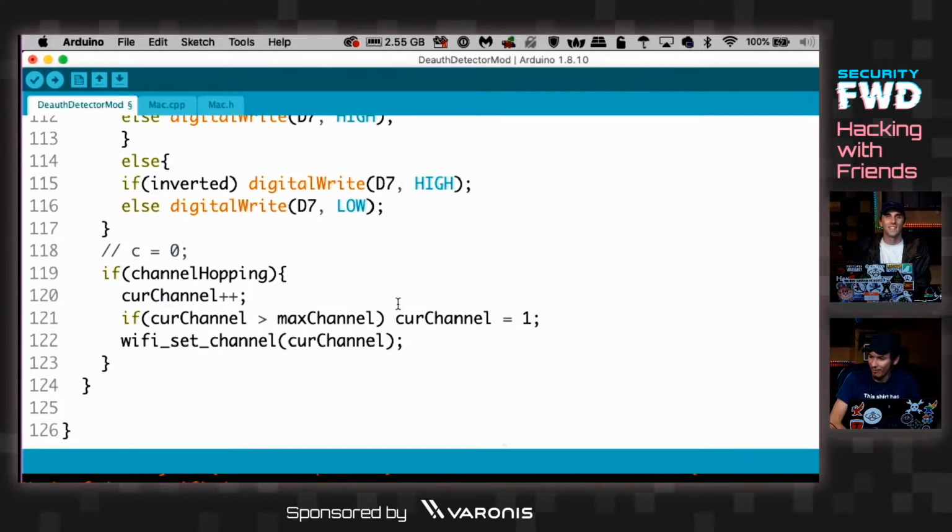Is there a defined amount of time for each cycle, or is it variable? No, it's as fast as this microcontroller goes. Okay, so 500 is kind of an ambiguous amount of time. No, 500 milliseconds is not connected to the LEDs. 500 milliseconds is how long between each scan, or each channel. I was thinking of the 500 score. Right, because you're counting down from that, and that's iterating each cycle. So you're not saying 500 milliseconds, you're saying 500 loops. Yeah, in 500 loops, basically, turn off the LED.